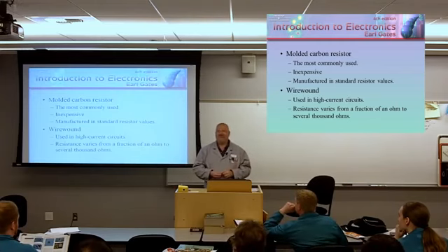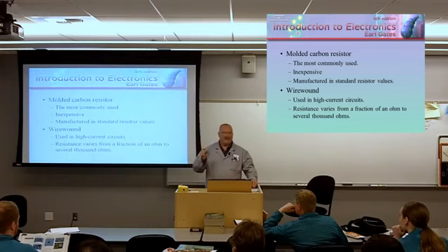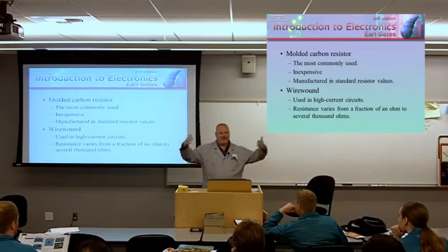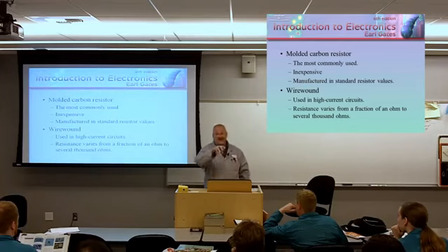One of the things they did is that the majority of boards that were rejected were because of a capacitor, because they used 20% tolerance capacitors. And the circuit would not tolerate that. It had to be right in the zone. So I would go to stores and get a bin of capacitors, test every one, and sort from 20% tolerance to like 5% tolerance and keep those capacitors. When I ran into that problem, I would just unsolder that cap and put the new cap in.